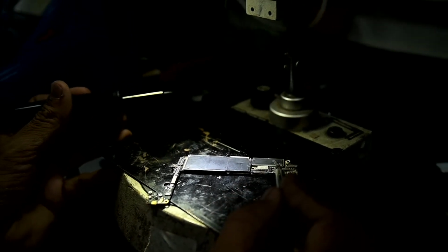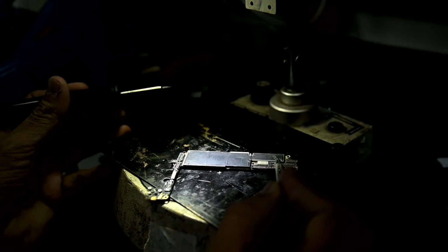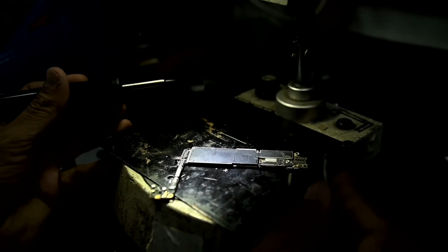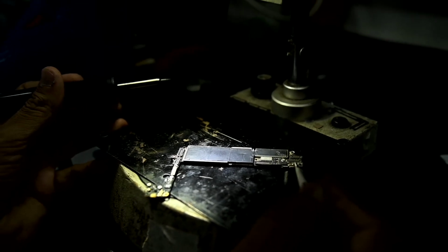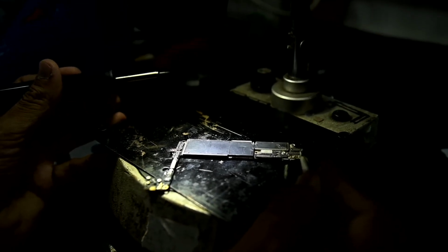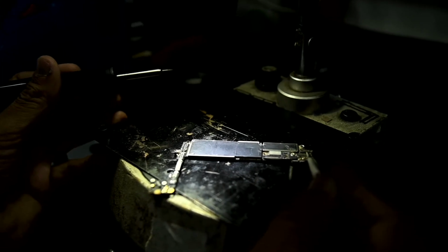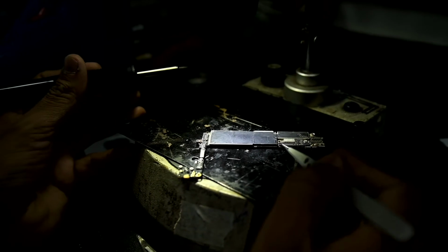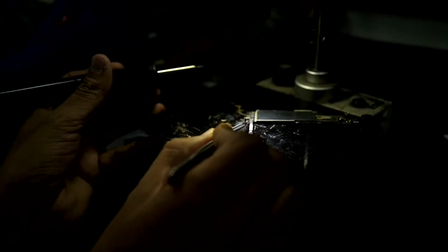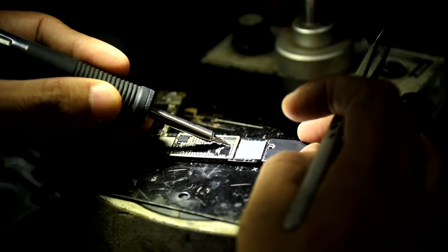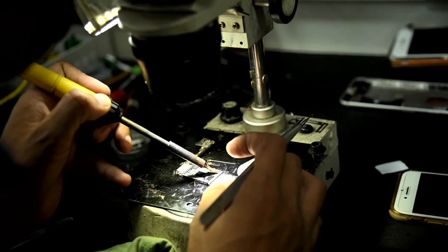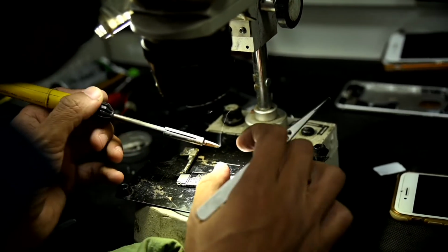This is the section for display ID, and this is for the charging IC. Charging IC section. These are the display and touch connectors. This is a touch or fingerprint touch connector. This is the dock. It has the charging port, ringer, and mic side. These are the camera connectors. Using a soldering iron, the disconnected tracks of the audio IC are repaired. It takes some time to make the connection.